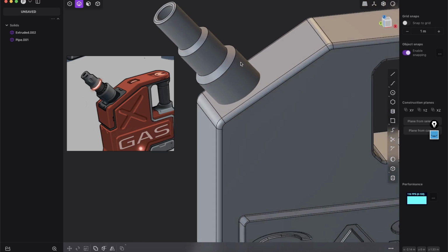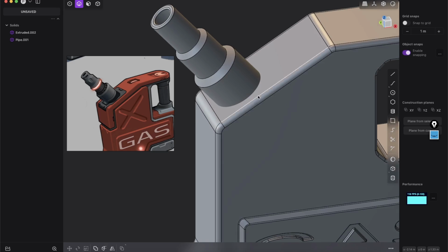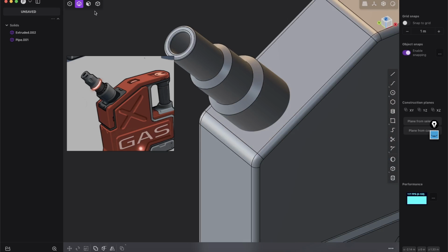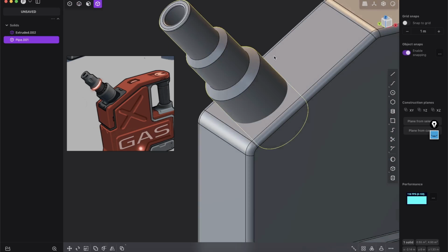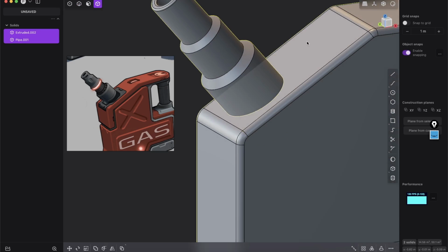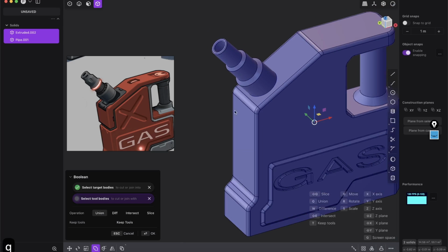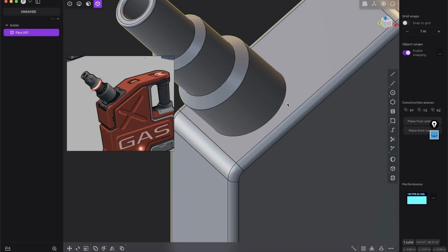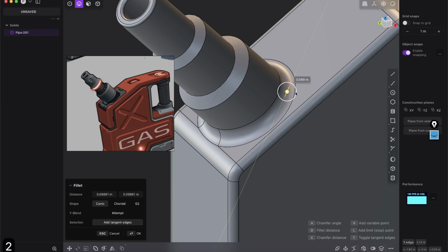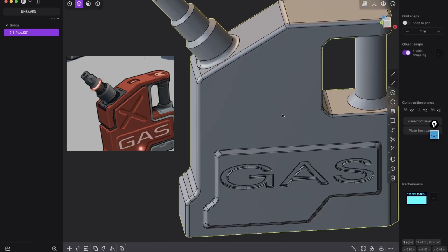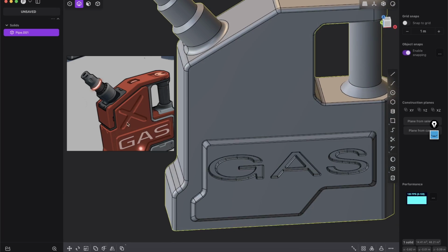And this is fine. And yeah, now you can do a lot, and for example, let's now combine those things. So again, press object mode and select this object and shift click this object. And again, press Q for Boolean and Q again to just add this into one body. Press OK. And now you can give here a fillet or something or add some cuts. Yeah, and maybe let me show you also just how we can create this X here.